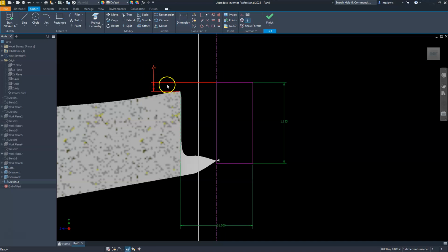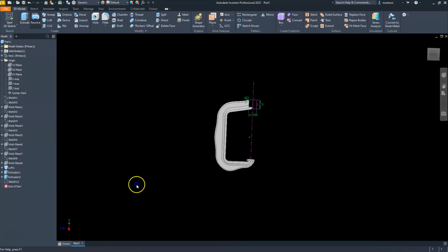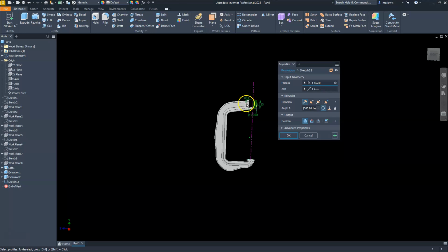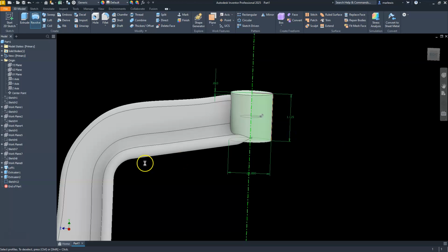Or we can bring it down. So this, the beauty of this is that we can kind of control where we want this block at. So if I want this to come down like 0.0625, I can do that and make adjustments on the fly. I think I'll leave it here. Let's go ahead and go to finish sketch. Once I hit the revolve, it should have two things satisfied. So it has the path already selected, and it has the, not the path, I'm sorry, the axis of revolution selected, and it has the profile. Let's go ahead and hit the OK button.